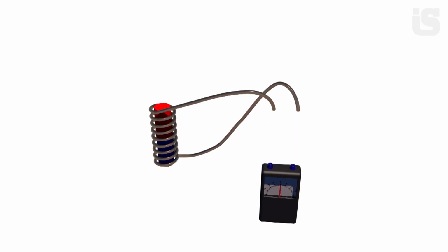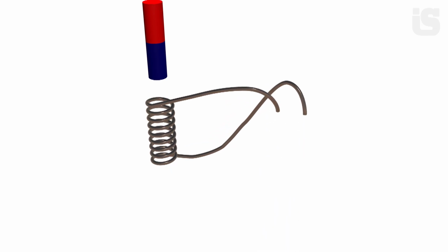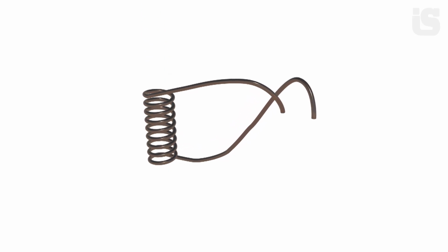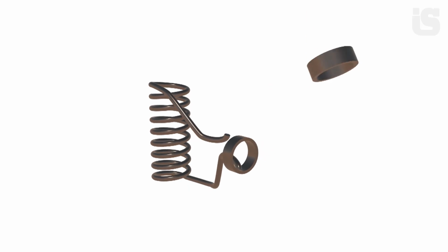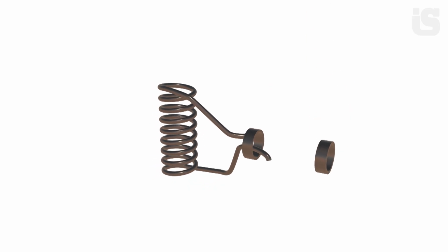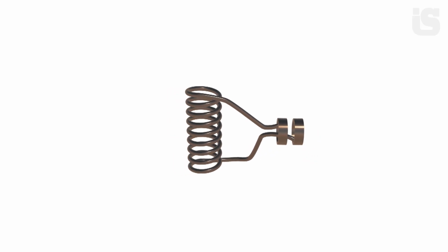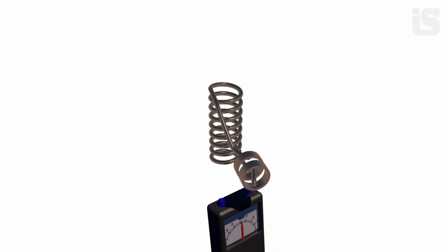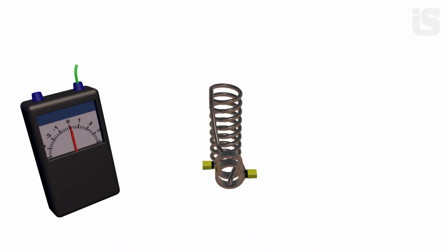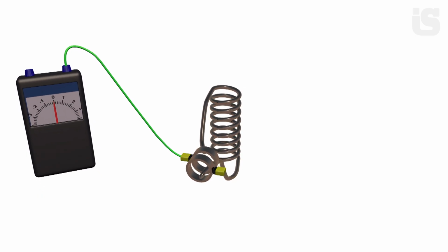Based on everything we've discussed so far, let's try to build an electric current generator. We already know how electric current is generated. Let's modify the solenoid slightly. Let's add 2 metal rings to the solenoid. And let's add current collecting brushes to the rings. The generated current will flow through the rings and the brushes.